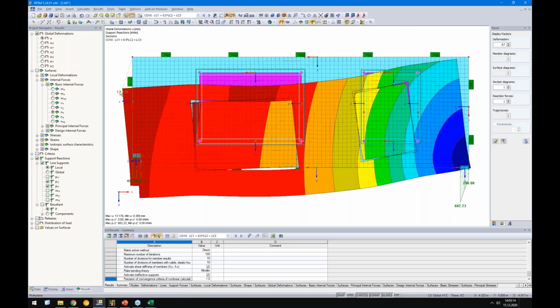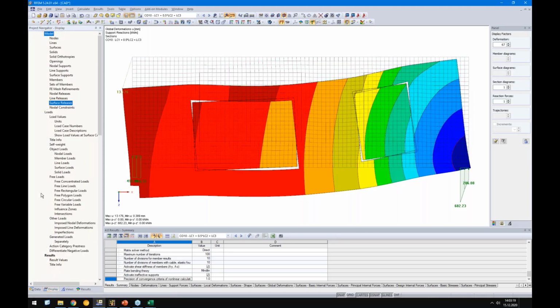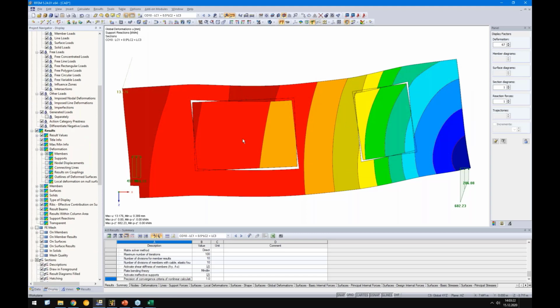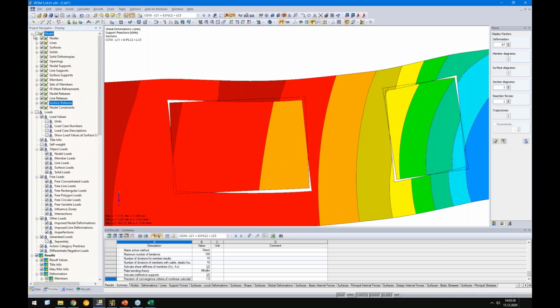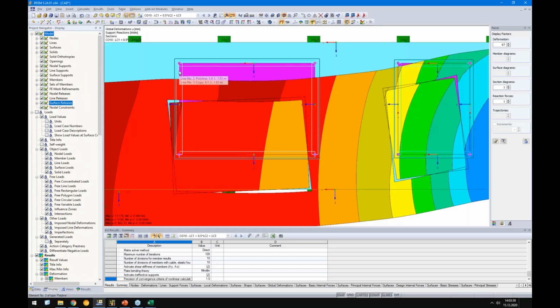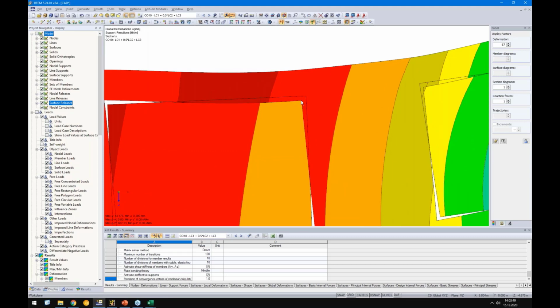Okay, so I didn't remember the deformation before, but that's actually not the aim. Let's check the deformation. First, it could be a bit confusing because the window is displayed inside the CLT wall, but that's clear. We have modeled the window, the rigid surface, directly to this wall element. So we do not model the gap, we consider it with a line release. And therefore, the distance now between this node and this node must be smaller than 1 centimeter.